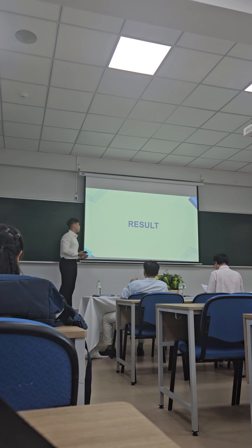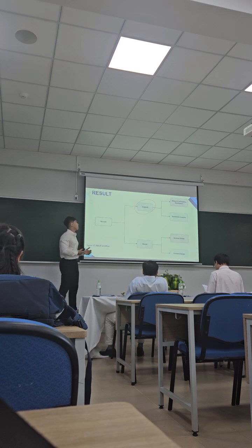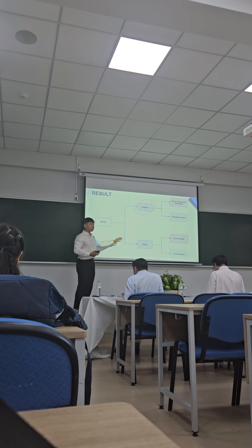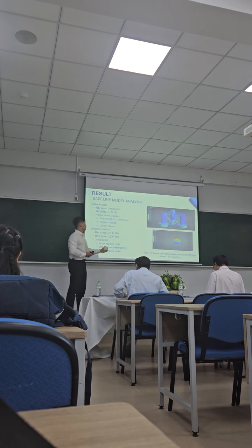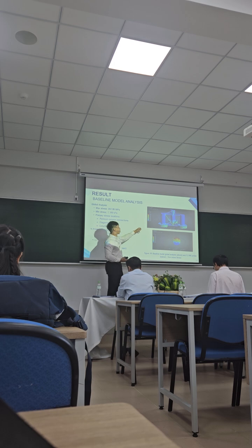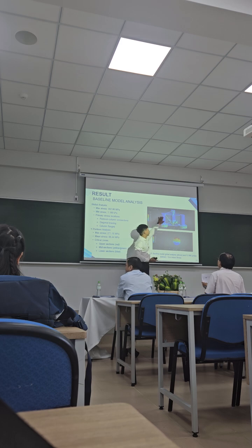Coming to the results, I will focus on the results of the analysis phases, including the global analysis of the baseline OC4 configuration, internal stress and deformation, and the sensitivity analysis. As you can see in figure 18, the baseline model can withstand the current loading condition. The high stress concentration is at the central brace connection, the base column, and the connection.